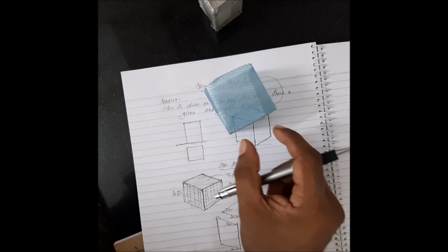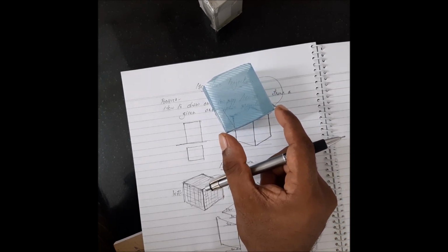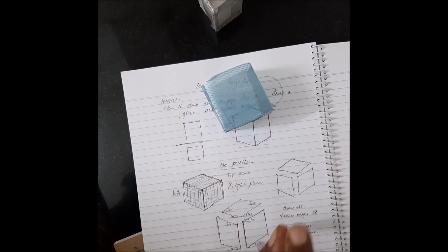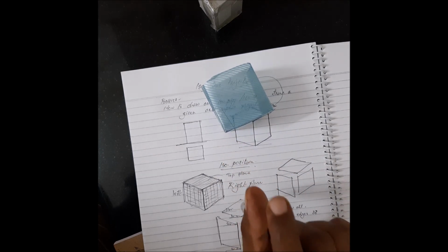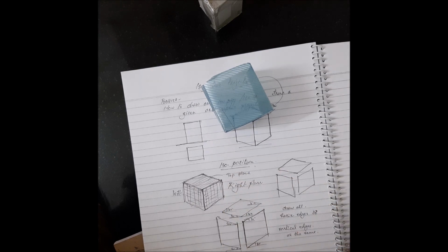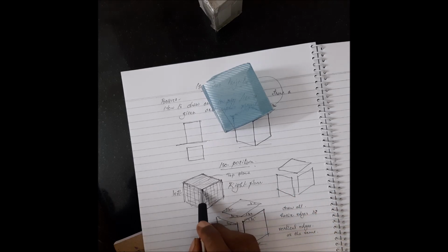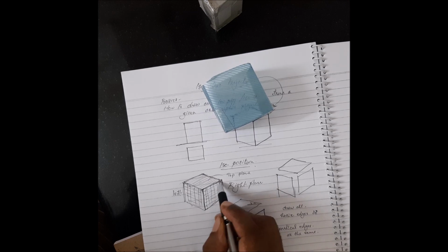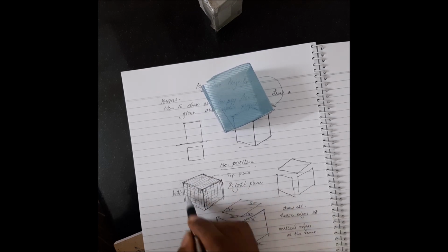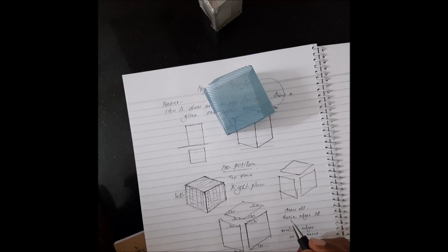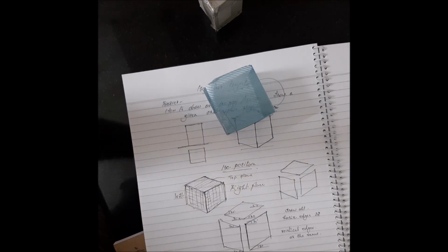Suppose this is 20 mm long or 30 mm long. That 30 mm will not be visible in the projection; it will be foreshortened, or shortened a little bit. Now our intention is to find out how much it is shortened. If you see the figure, you can see that all the edges of the cube are equally foreshortened. This edge, this edge, this edge, all these edges are equally foreshortened. Now our intention is to find out how much it has shortened. There is a method for it, I'll tell you.